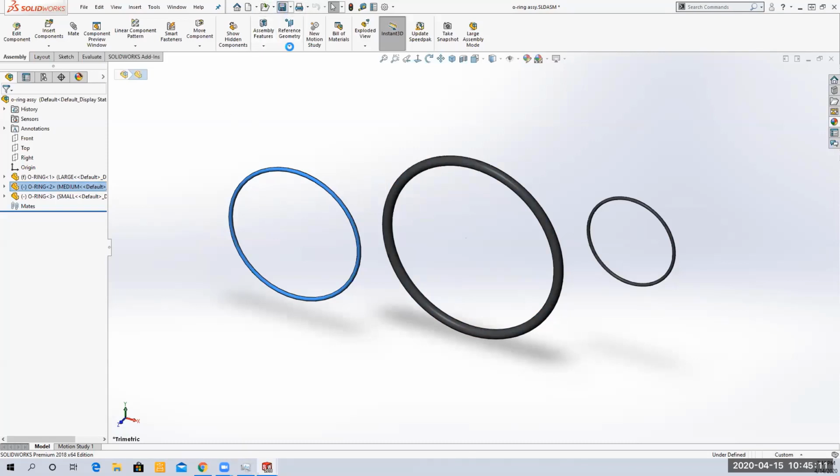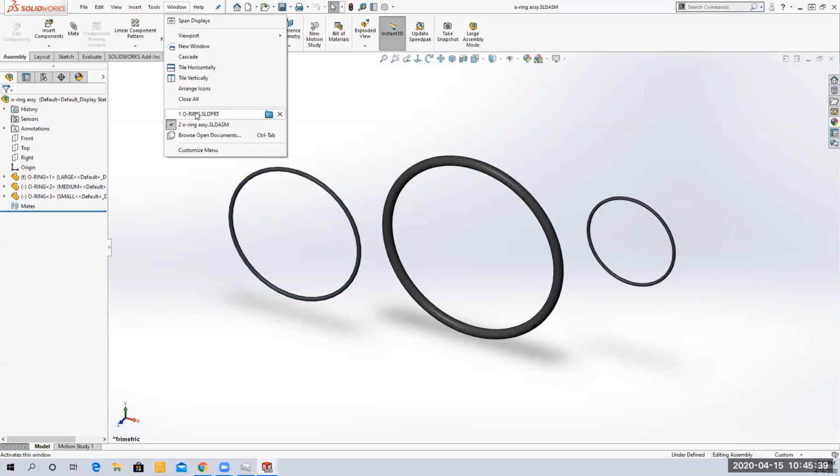And I've done that with labels where I'll have different versions of the same label. So I might have a serial number label and a part number label, and they're different sizes and they show different text. And you enable one text and you suppress another text, and it makes it really, really cool. And so I really like doing it that way.